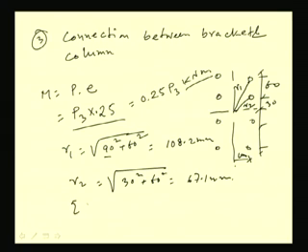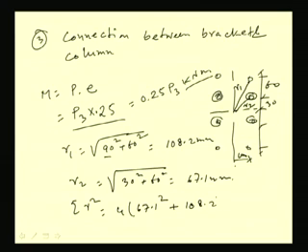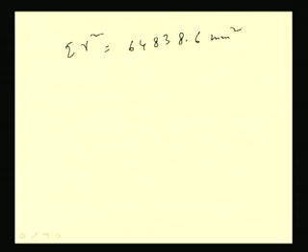So, if we see summation R square, that will be 4 rivets similar, this rivet, this rivet, this rivet, this rivet will be same. So, 4 into (67.1 square plus 108.2 square). So, this will be the summation of R square, which is coming as 64838.6 millimeter square. So, summation R square can be found from this formula.